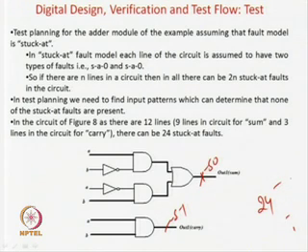If you are thinking about the general fault case, there can be n number of defects. This line can be shorted, this line can be shorted with this one, this OR gate may be converted into an AND gate because of a fabrication defect, this NOT gate may become an inverter. So there can be an infinite number of faults possible in this circuit. If you want to test for all, you will go mad in time, you cannot do that. So structural testing tells you not to think about the functionality and not to think about all kinds of defects that may take place. Only think that some particular type of faults are there, that is the stuck-at fault, which is called the fault model.